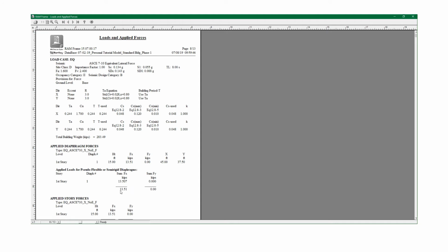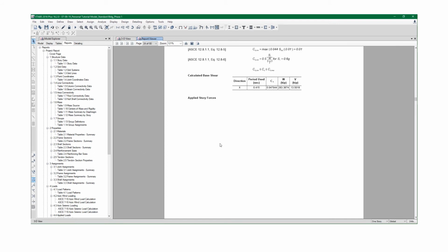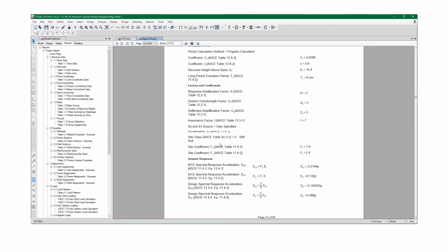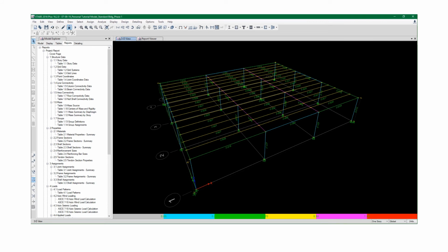Multiply that by effective seismic weight, gives us 13.51. 13.51. All right, same Cs factor. So we have converged with our lateral load analysis for these two models and our gravity load analysis, and we could look at it in greater detail, but I could tell you it works.